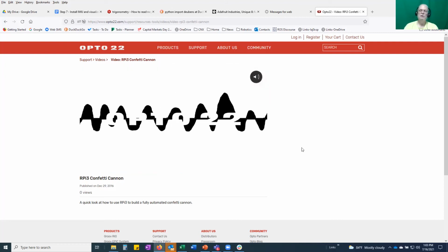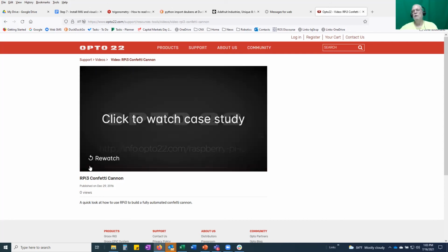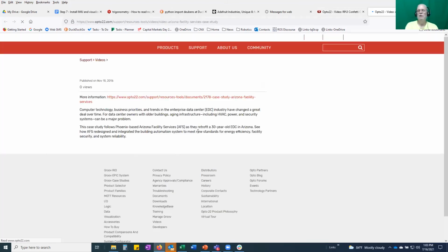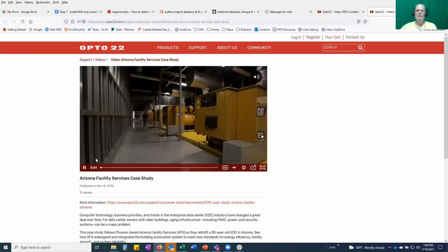But the problem is, once they do that, people think, well, I'm going to run that the full length of my vehicle. Now you're running I²C a long distance you shouldn't be. So SparkFun came up with the concept. They got these little adapters you plug into the Qwiic interface, and then you use an Ethernet cable as the long distance cable, and you put a module at the other end and convert it back to Qwiic. So it's real handy, but then everybody thinks they should use it for mainline communication on everything.